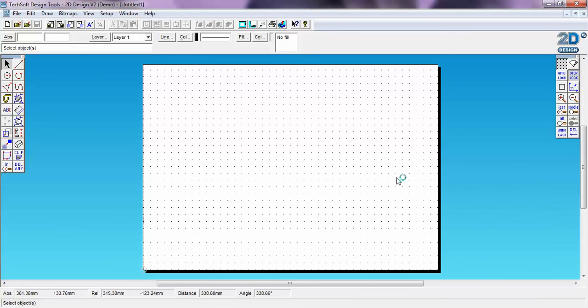Okay, so the Dim Lines tool is essentially a tape measure. You use it as you would a line tool. You select it, then hold down and drag to the required length. However, now you then drag it outwards as such and click again to release. Now here you can see the measurement, which is 111 millimeters, which is the measurement of the line.